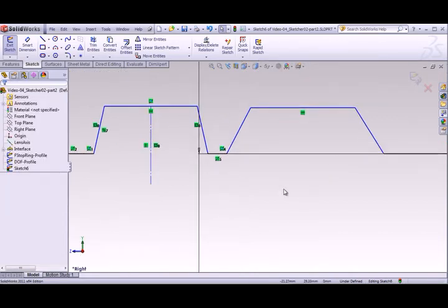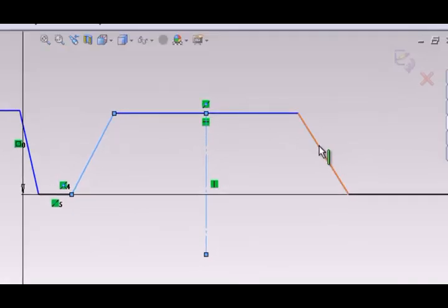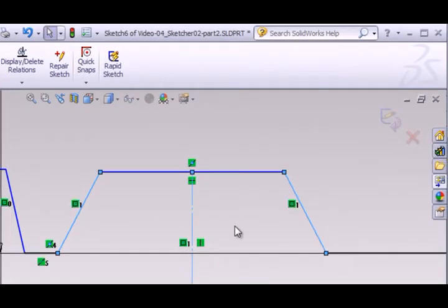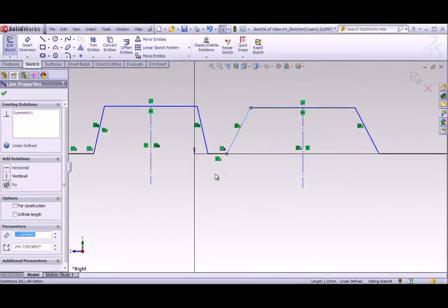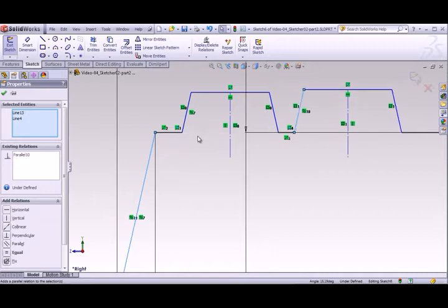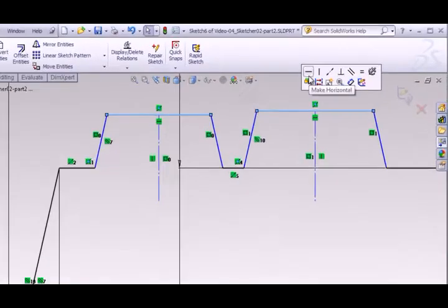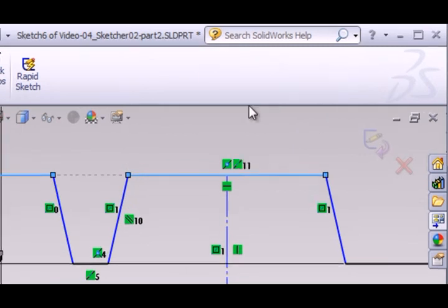Now just to practice that, let's do it again right over here. So we'll drag a vertical line straight out, right-click in the viewport and say Construction Geometry, Control-click the three lines that we want to be symmetric, and click Make Symmetric. Now I'm going to select this front edge, make it also parallel with the front edge of our shape. Take the top edges, make those coincident to one another, or collinear.